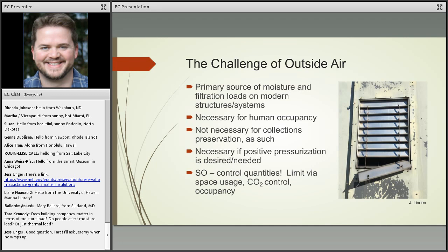It was a fairly standard design consideration to think about positive pressurization in spaces in the past. And the only way that we can get positive pressurization is to bring air from someplace else, which is typically from outdoors. So we bring that extra volume of outside air in order to positively pressurize, or if you will, blow up the interior space with more air than it can hold. And as the air tries to escape somewhere, it leaks out of the room, which means that all of our conditioned air is leaking from the room rather than bringing unconditioned air into the room.